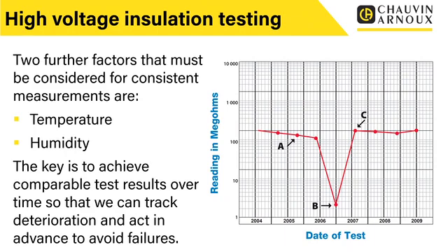So sometimes when we carry out a test, we may find that there's a problem with the insulation resistance due to humidity, but actually that's just a temporary effect. Once it's been dried out properly, then it's okay again. So it may be something that's actually reversible.